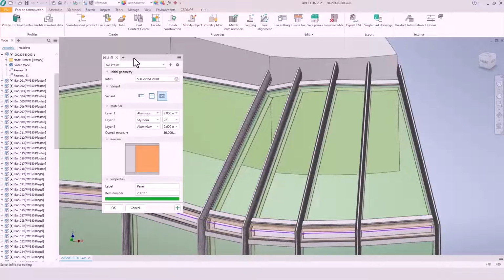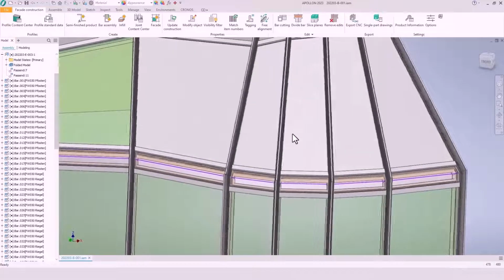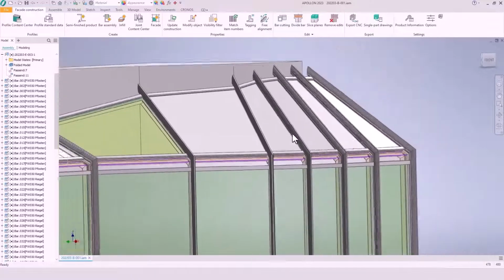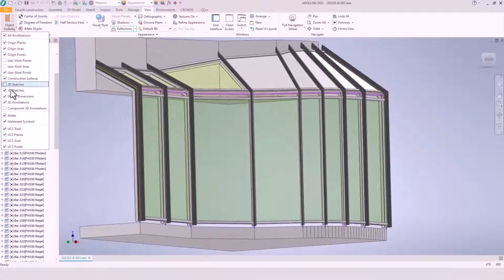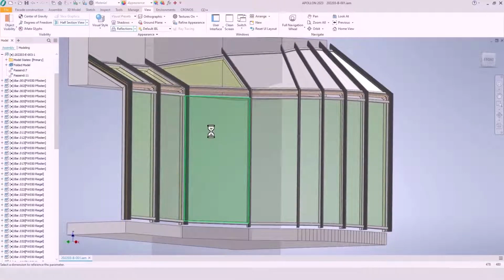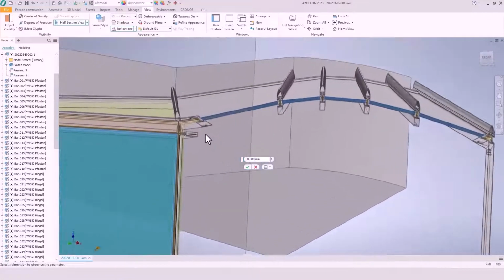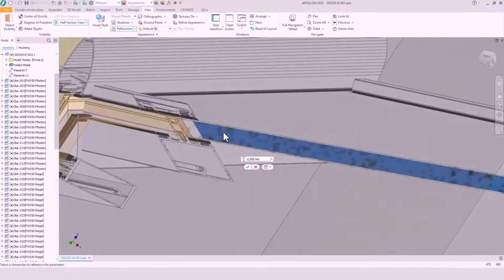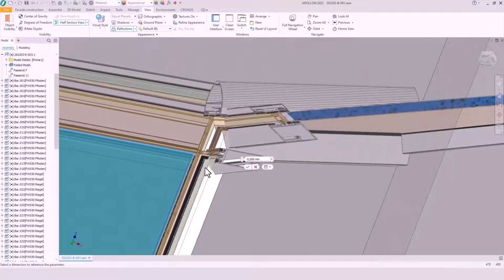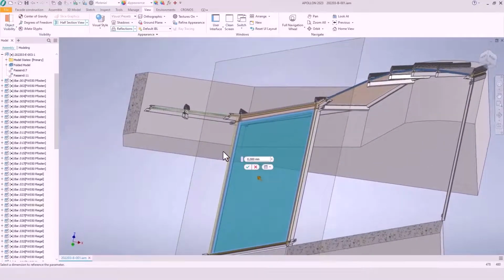So APOLLON is changing the insulating glass to the aluminium panels. And also, of course, the gaskets of the profiles are changing to the new thickness. So we hide the 3D sketch and I do an APOLLON live section, and also the display of the fillings has changed. We take a closer look at the filling, and the fillings are now not just simple solids, but objects with a high level of detail. Here we can see the aluminium panel section with the special materials.